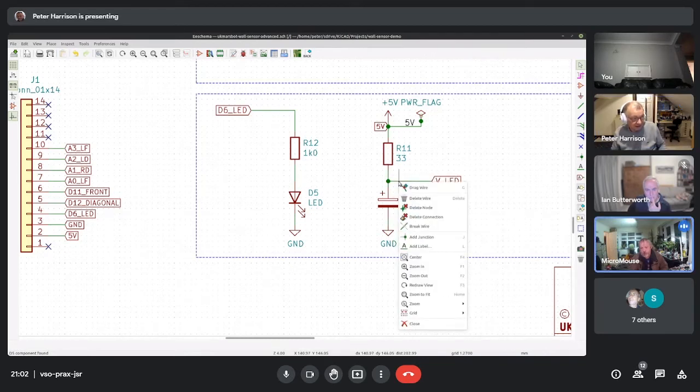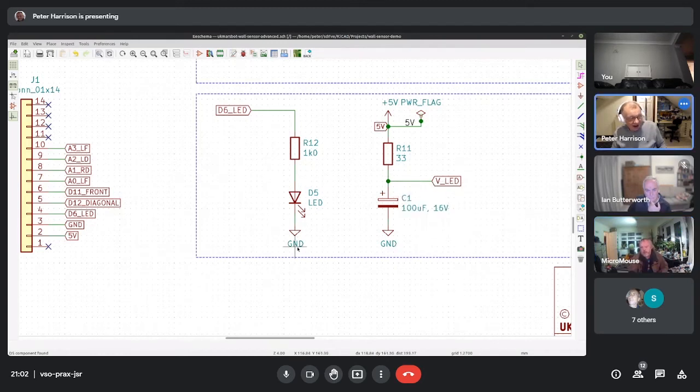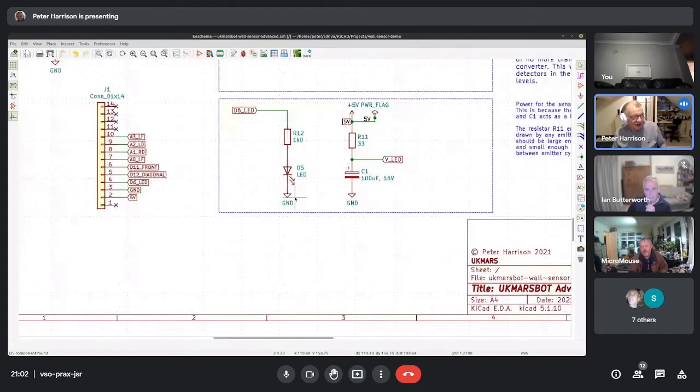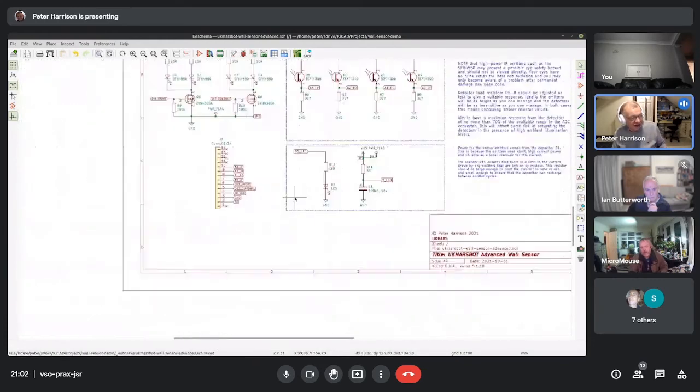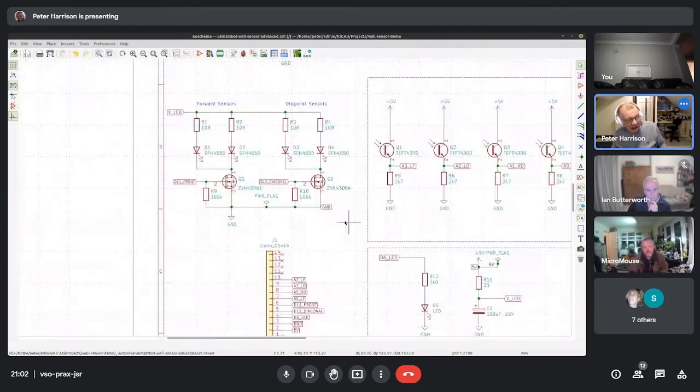Right. But obviously the question is whether that ground and that other ground will be connected together. They are. And I think the names on here do indeed imply the name of the net, right? Because they are connected together. So yes, I was not following what you were saying. They are connected together. The specific error is just about having unique labels. Right. It's not that this is not called ground. Okay. It's that this label is lonely and needs a friend.